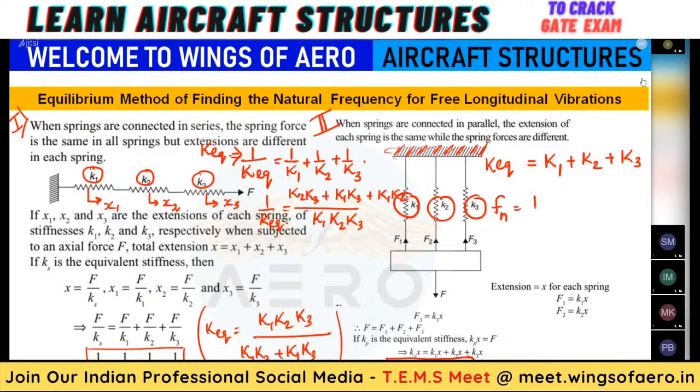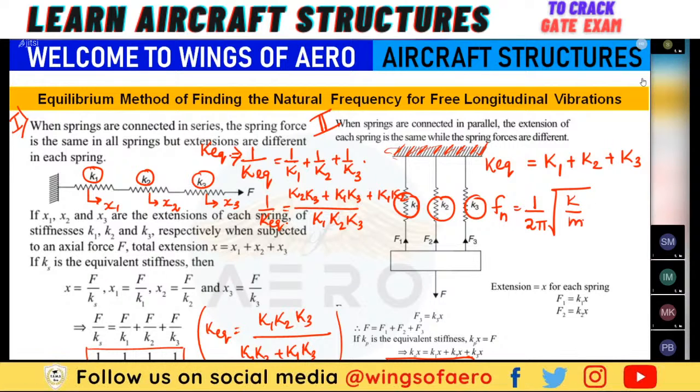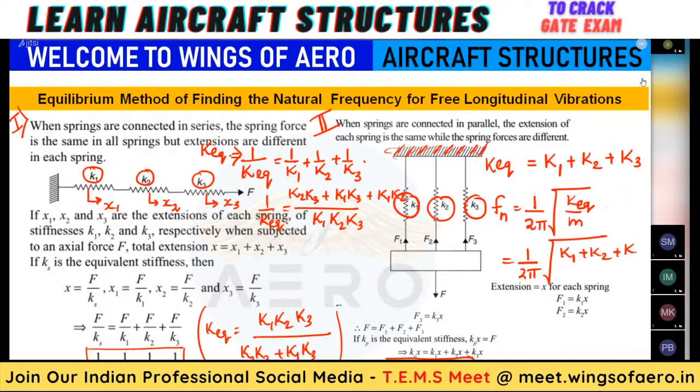Now, if they ask for this same system to find the natural frequency, you know the formula for natural frequency, that is 1 by 2 pi root of k by m. Now, you might have a doubt about which k we should include here. You should include the k equivalent, right? So it should be 1 by 2 pi root of (k1 plus k2 plus k3) by m.